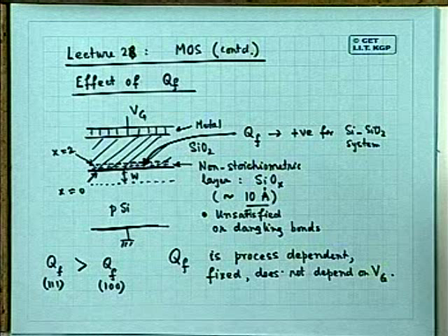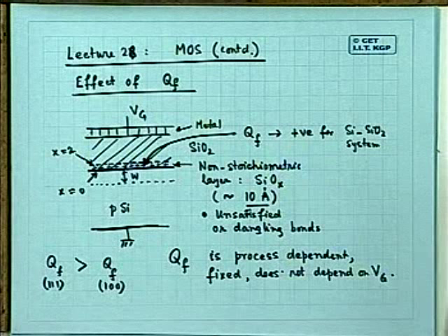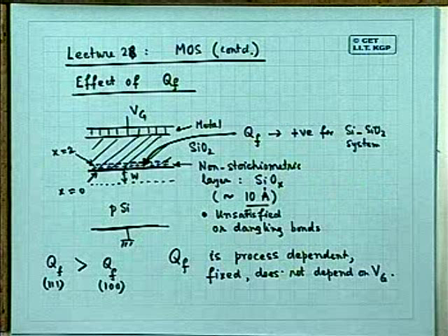So if I make such a device, an NMOS, that is, we place an N plus here and N plus here, what will happen to this device? When Vg is equal to 0, the device will conduct. Such a device will naturally come as a depletion mode MOSFET. In fact, that was the difficulty of NMOS technology in the beginning of MOS technology.